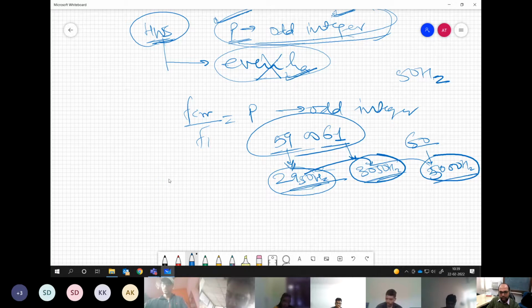Now when I say even harmonic, I do not mean second harmonic, fourth harmonic and all that. No, that's not applicable here. I'm talking about some higher order that I will come to shortly. But the difference would be that just by keeping this kind of ratio instead of an even number, you will get rid of a set of harmonics which are called even harmonics. You understand my point? So this is the second condition which we are having for our pulse number P.